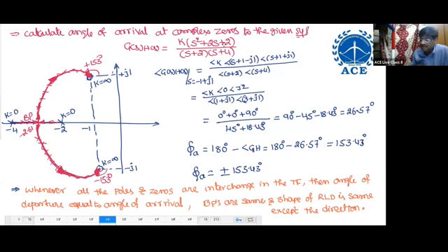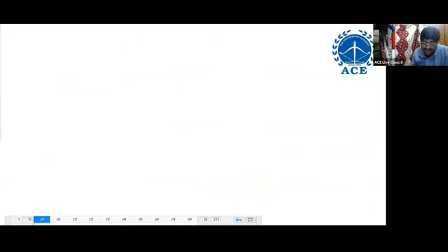So these are the construction rules of root locus. The rules are completed. Now we'll solve the problems. In total there are 8 rules to keep in mind. First, symmetry; second, number of root locus branches; third, real axis root locus branch; fourth, asymptotes; fifth, centroid; sixth, breakaway point; seventh, intersection point with the imaginary axis; eighth, angle of departure and arrival. Everything should be in the mind.